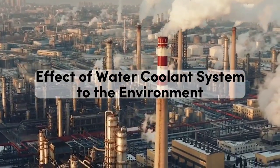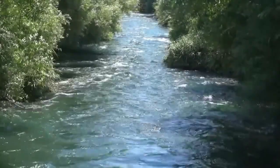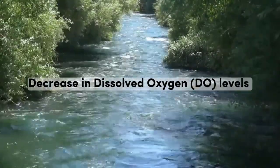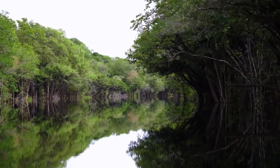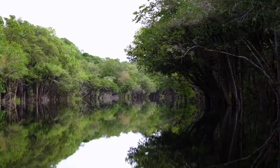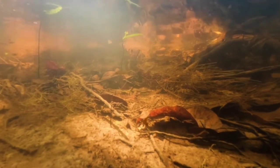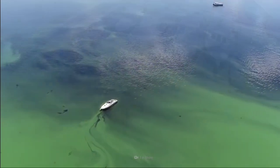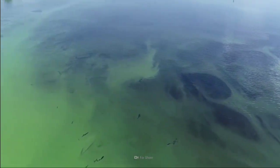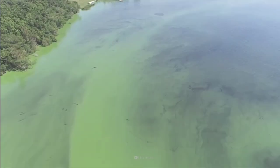Effect of the water cooling system on the environment. Decrease in dissolved oxygen levels. The warm temperature reduces the level of DO in the water. Warm water holds relatively less oxygen than cold water. The decrease in DO can create suffocation for plants and animals, which may give rise to anaerobic conditions. Warmer water allows algae to flourish on the surface of the water, and over the long term, growing algae can decrease oxygen levels in the water.